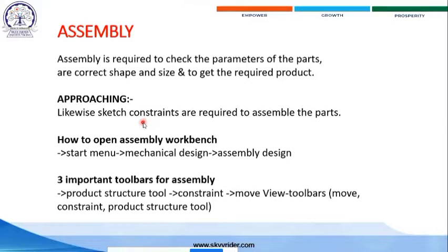And as you know, regarding constraints and degrees of freedom, in 3D there are 6 degrees of freedom, isn't it? 3 are rotational and 3 are translational. We have to restrict those 6 degrees of freedom so that we can maintain the exact given shape and size of the profile, and maintain the assembly in an appropriate manner.